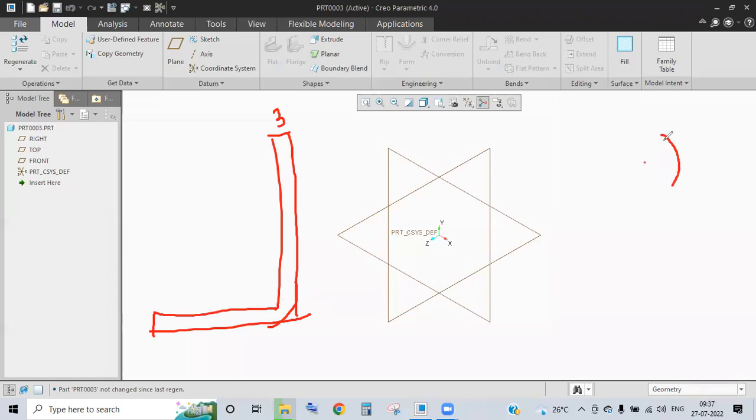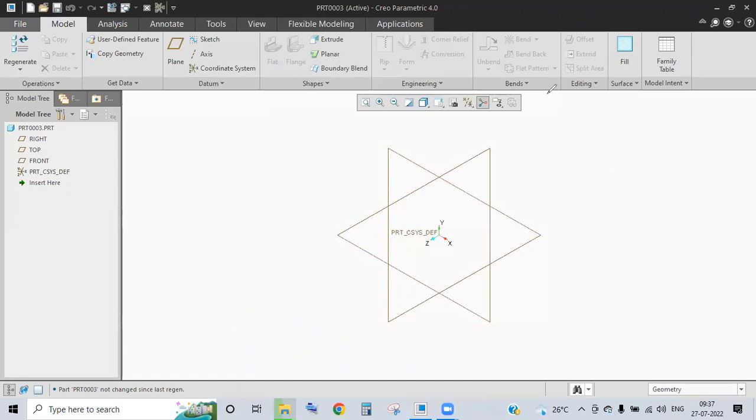Its radius will be decreasing. The radius of this is 3 and you are offsetting 3 mm inside. That means when it goes here, it will be a straight and sharp edge. Those kind of things cannot be manufactured. So that is the reason by default they'll give 3 in inside or inside radius. There is no way that outside will be a sharp edge, because when you are offsetting away from the center, obviously the radius will increase, it will not decrease. So you should be careful with that.